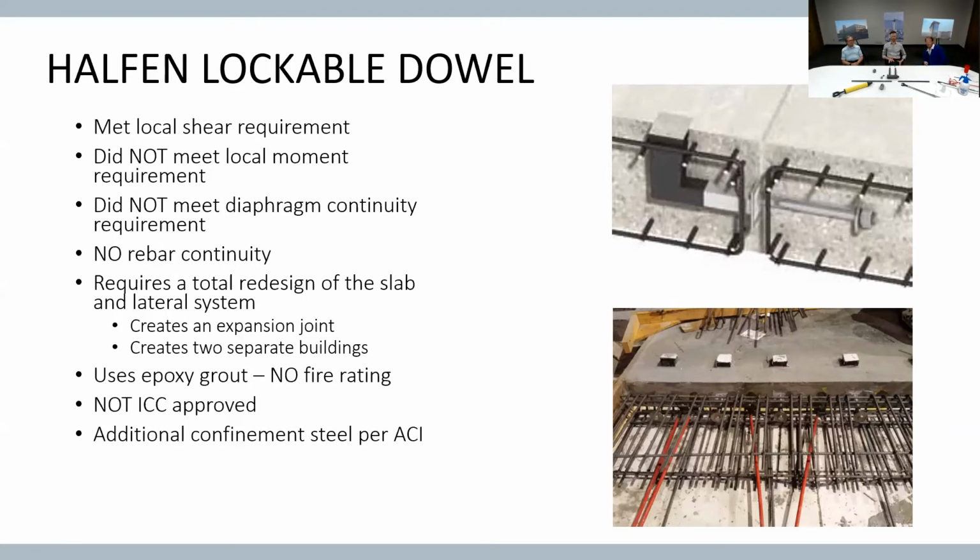And the other thing we found is a lot of folks don't really realize the epoxy itself. What this system uses is an epoxy filler right through here to lock this thing together. In most of the buildings we do, we have a fire rating requirement of at least 1 hour, and a lot of times 2 hours, and around 200 degrees Fahrenheit, the epoxies go into what they call glass transition, or it gets soft, and you can't get a fire rating with epoxy systems like this.